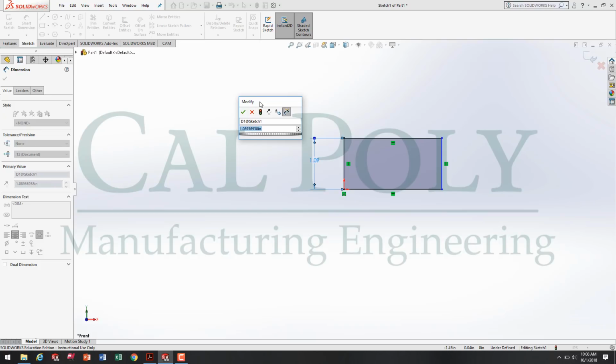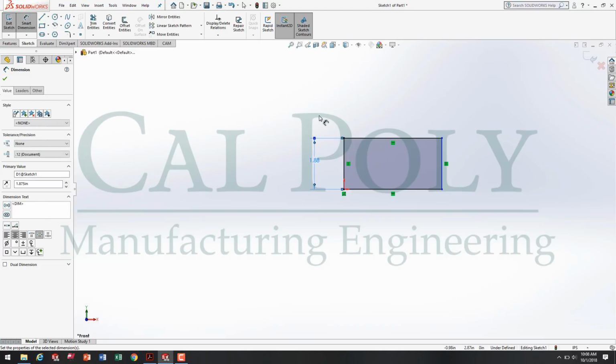This dimension displays 1.089 inches. To change it, I simply type in the dimension I would like to obtain, such as 1.875. Enter. What that does is it goes ahead and changes the dimension and scales the rest of the sketch based off that dimension.